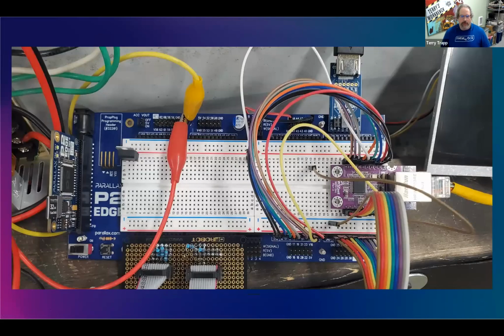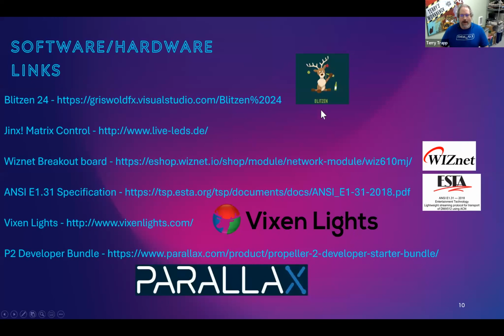Let's see here. Here's what the overhead looks like of it. There's the WizNet board that I'm using. I'm not using SPI to pull the data out. It is a parallel bus. And so with the parallel bus, I assumed I could get data out faster. At this point, I'm not sure if that's true or not, just based on the fact that I had to put a lot of delays in there to be able to read good data out of it. I don't know if it's faster or not.